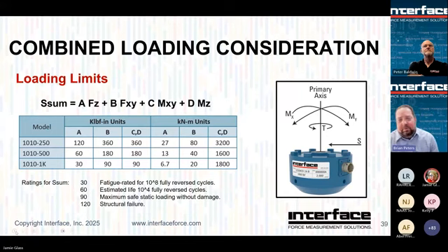So we've been building low profiles for a long time, and some of you that have been using them for a while know that this is one thing we do, but we actually moment compensate every single low profile that we make. So moment compensation is a method of bolting the load cell down to a fixture, hang a weight off, usually about a foot off, pretty high weight. We swing that weight around and we see how the load cell signal changes. Okay, now that's going to give you confidence that if you throw it into a basic application, the load cell is going to do a good job to not be influenced by any off-axis loads and give you good, accurate measurements from the axial component.